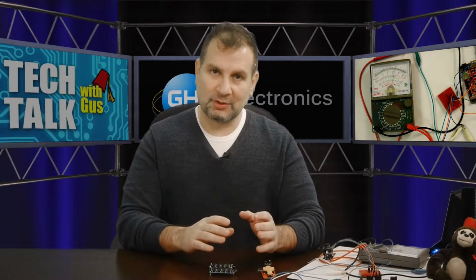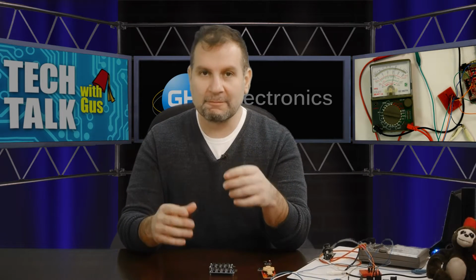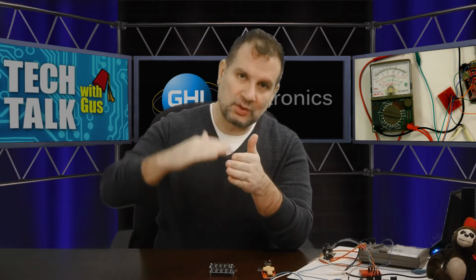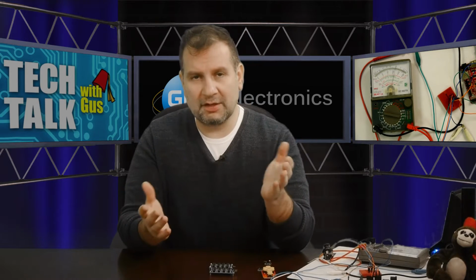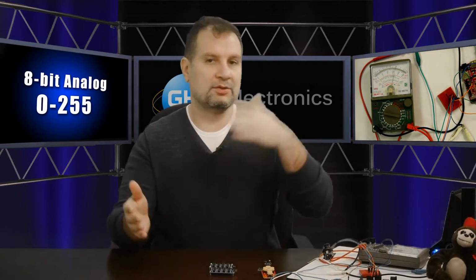But that would not work when, let's say, you are measuring temperature or certain values. And this is where we need analog inputs. Those analog inputs have special circuitry inside the microcontroller that takes that voltage level, usually between 0 and 3.3 volts, and encodes it to a digital value. If you have an 8-bit analog input, that would be from 0 to 255. That's the range we have on a byte.